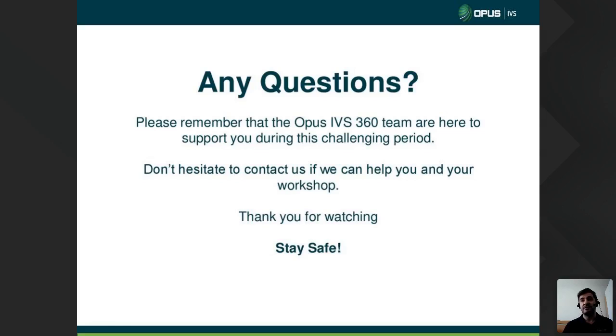So the percentages I've never relied on, because I've seen it even on known good vehicles, where the reset hasn't actually happened on the system. It still reads a certain percentage load that doesn't make sense for a new DPF system, for example. So I wouldn't rely on the percentages that inferred an open loop. I wouldn't use them as a means of diagnosing the DPF condition. Hopefully that will answer your question, David.